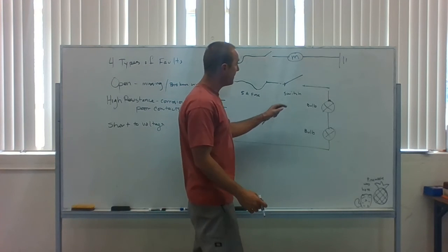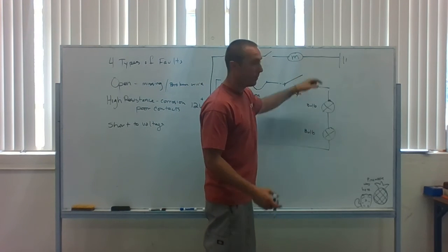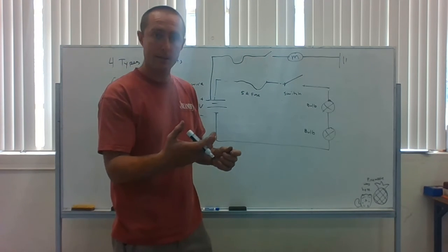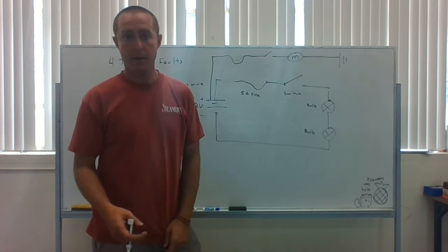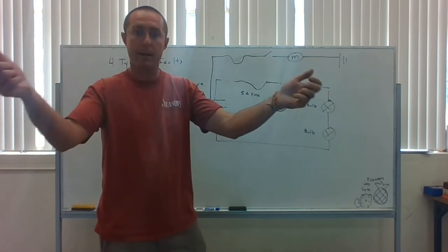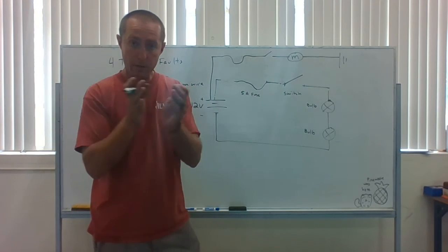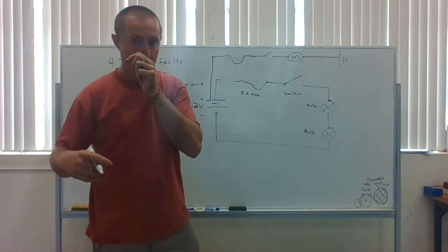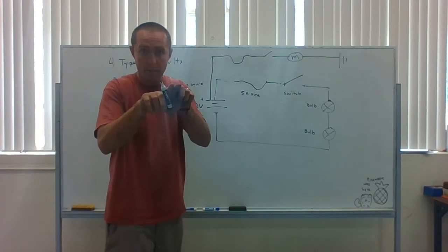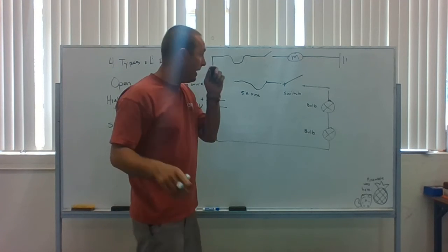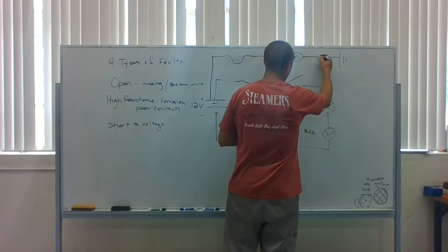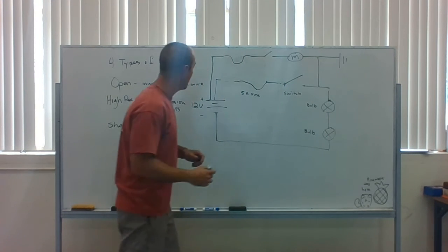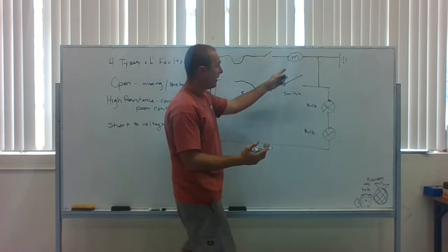And for whatever reason, these two wires were run in the same piece of conduit along my rail to either the headlights or the blower motor for the AC. So they ran together and then they separated later in the circuit. They weren't touching, they were just all zip tied to the same rail. Well, those two wires can rub against each other and actually make a connection. So accidentally, these connected.